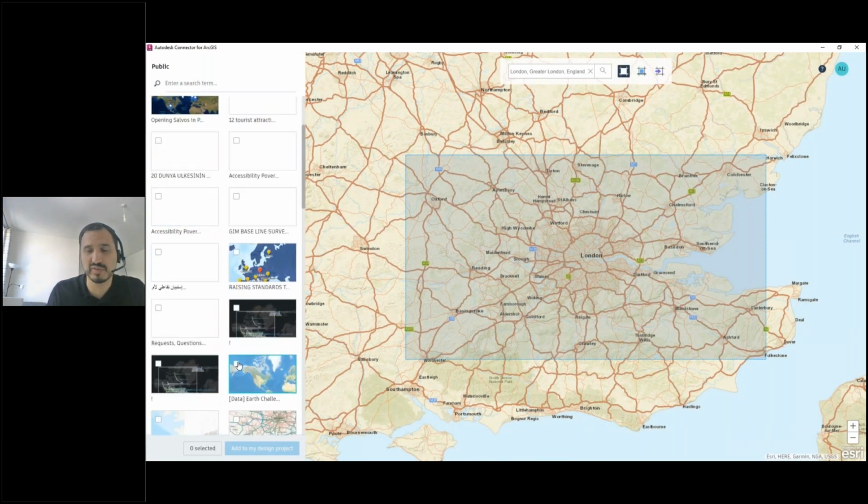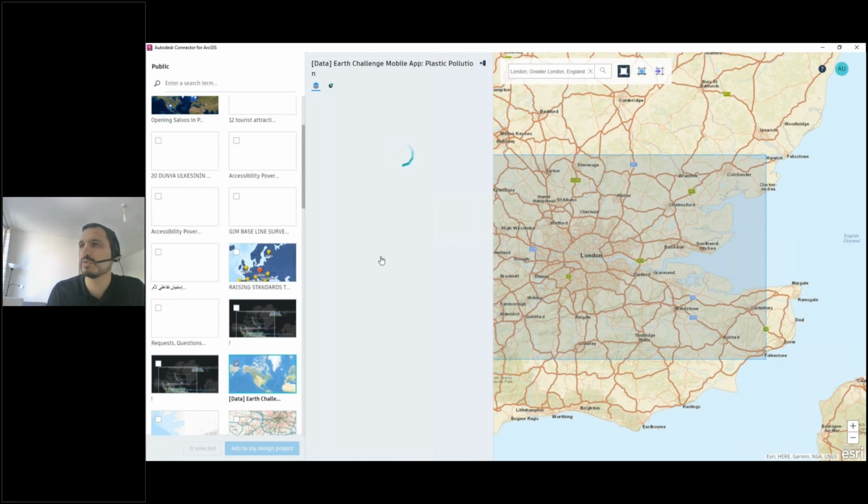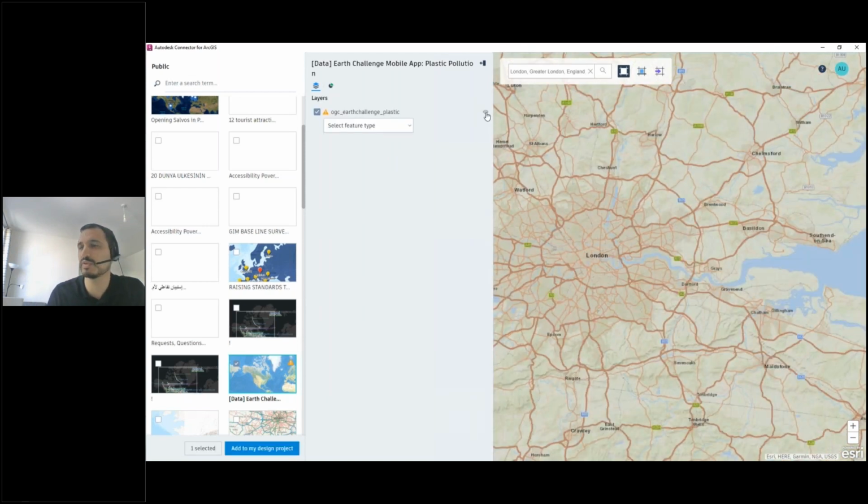And I'll show some examples of different objects that we can import and how we can pick the styles. We can perform queries as well based on the properties. So here we have a number of points. We can import them as AutoCAD points, COGO points, or structures. Those would be structures for a pipe network. I'm going to start with AutoCAD points.